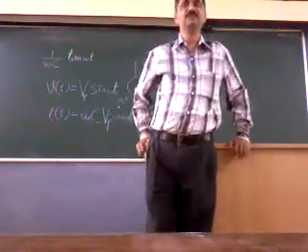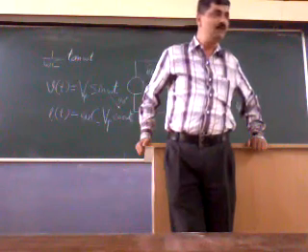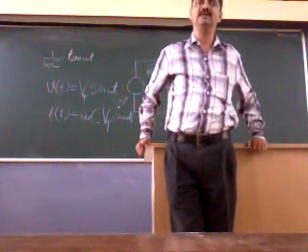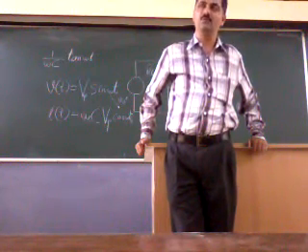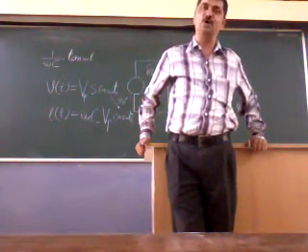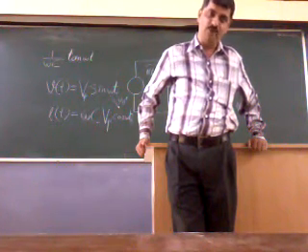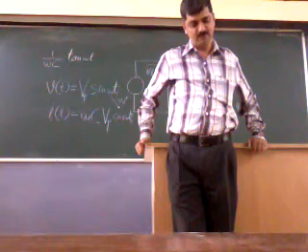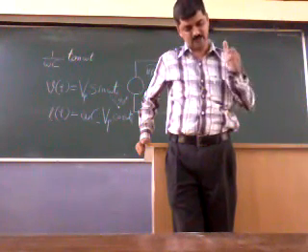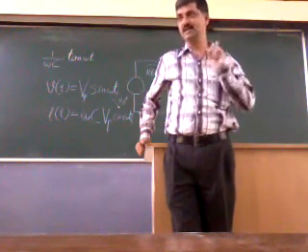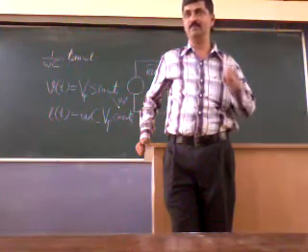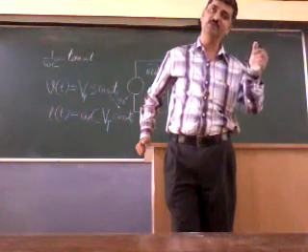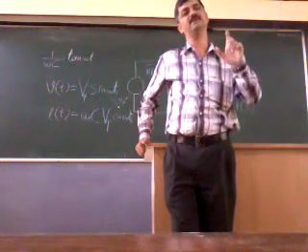But now, since we have components which exhibit a linear relationship between voltage and differential of current or vice versa, what we find is that everywhere, at any point or across any path, the voltage and current would be sinusoidal, but they would have different amplitudes and different phases.